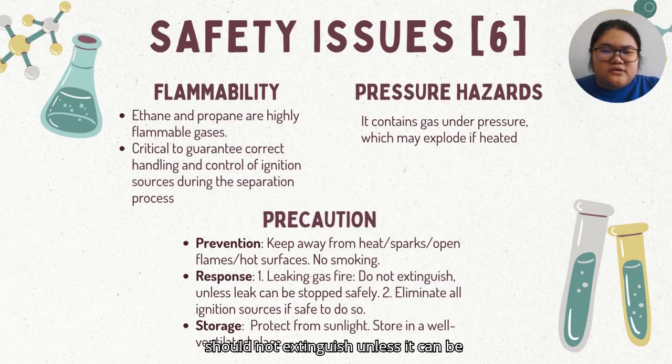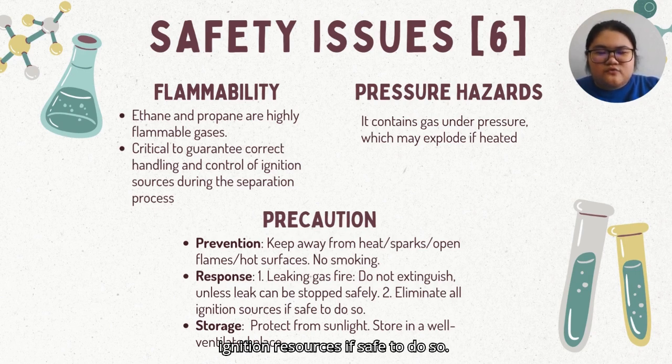Besides, we should not extinguish a gas fire unless the leak can be stopped safely when they are leaking. We should also eliminate all ignition sources if safe to do so. For storage, we should protect it from sunlight and store it in a well-ventilated place.